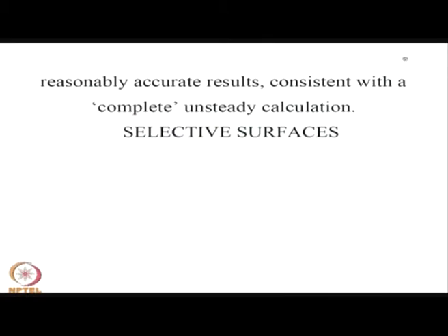And this is most important from the point of view of whether the collector will reach the required temperature before the solar radiation reaches the critical level of radiation. It can be more, but it cannot be less, because the critical radiation level corresponds to the temperature at which the energy delivery is desired by you. So, the collector has to reach the temperature before that time.